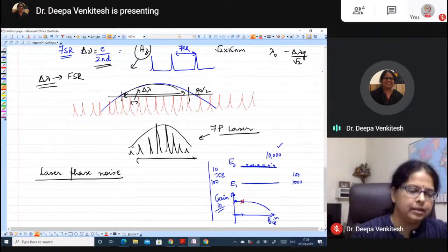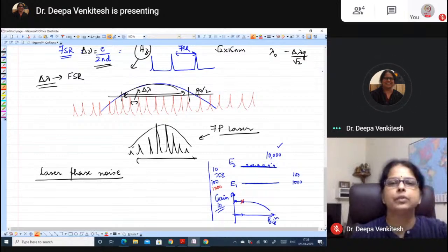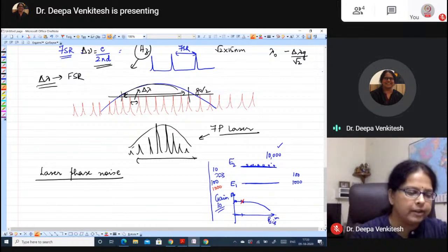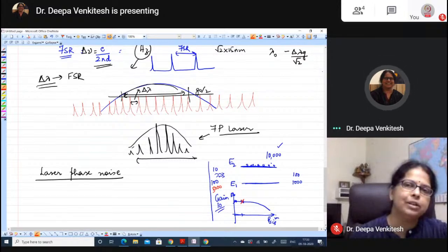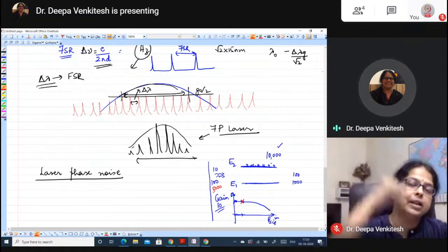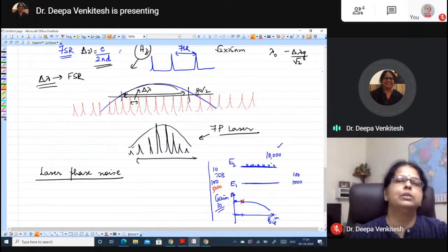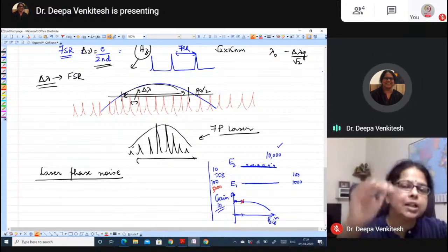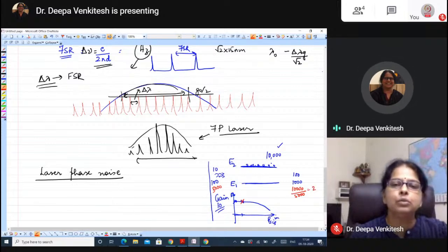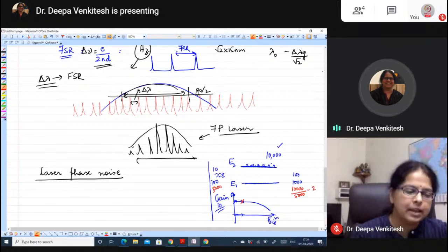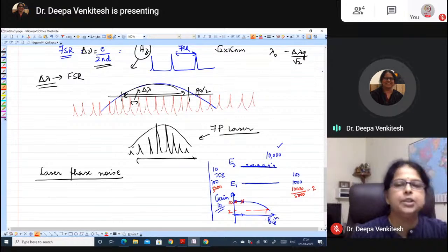Now, further increase: let's say I go in with 5,000 photons. Now, to maintain a gain of 10, I need 50,000 photons at the output. But look, I don't have 50,000 ions in the upper state. I have only 10,000 ions in the upper state, which means your gain starts to fall. I can get only 10,000 divided by 5,000, which means I can get only a gain of 2. So this gain, which was 10, suddenly dropped to 2 when I came to a larger input power.